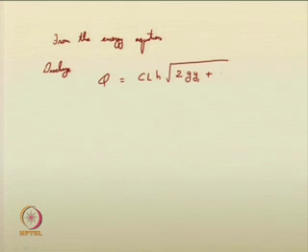So, from the energy equations, it is understood that discharge, say for a vertical sluice gate, can be given as C L H root of 2 g times y 1 plus, if alpha, the energy correction factor, is significant, you need to incorporate it, alpha V 1 squared by 2 g.